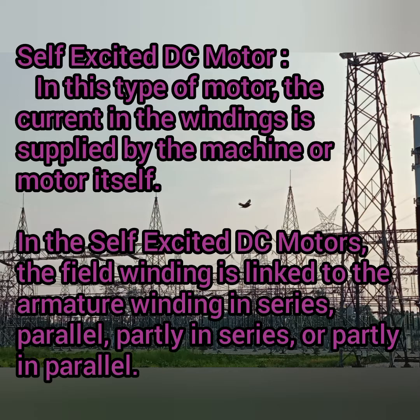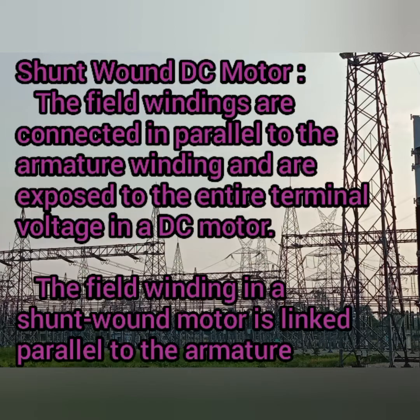So in a self-excited motor, the field winding is linked to the armature winding in a series or a parallel or a partially both are combined together. Then shunt wound or a parallel wound DC motor, the self-excited motor's subdivision, the field winding are connected in parallel to the armature winding and are exposed to the entire terminal voltage in the DC motors. The field winding in the shunt wound motor is linked parallel to the armature winding.